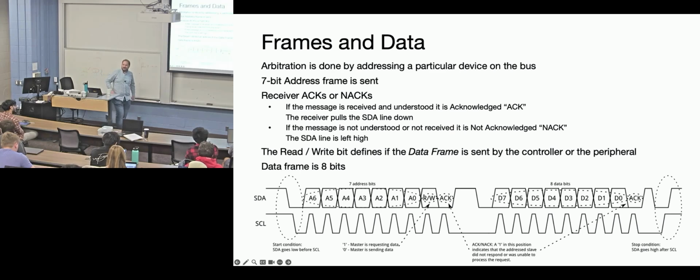All right, what do you think? It's kind of an open-ended question. Any ideas? So my assumption is that the clock is fine, but maybe the packet is a different size than it needs to be. It could be. So there could be an actual protocol reason, like, that's not the address. I wrote this address, and that device is not at that address, so it's going to NACK.